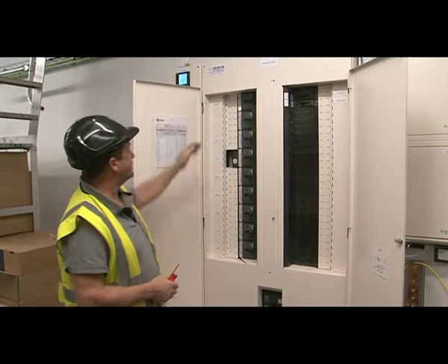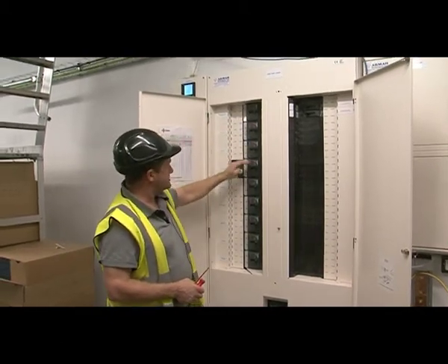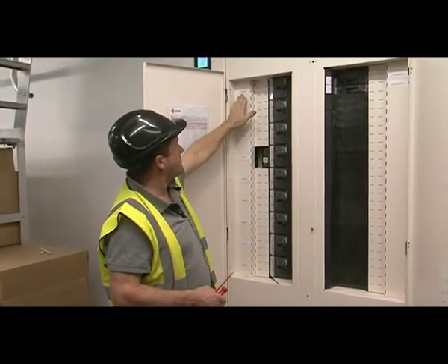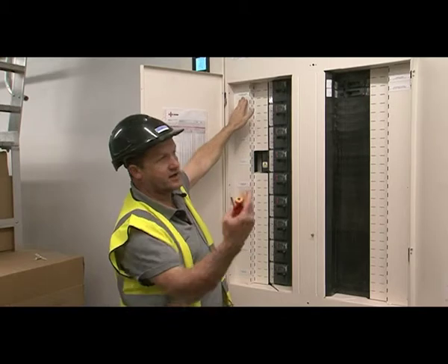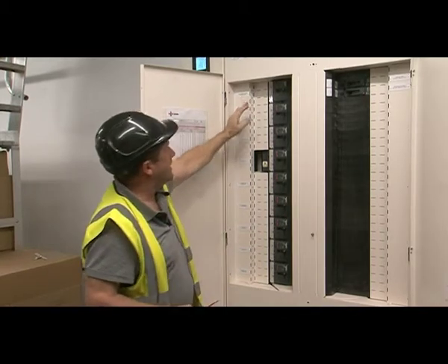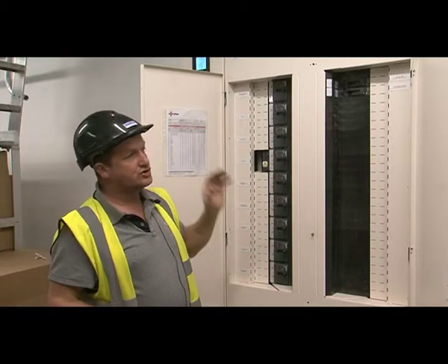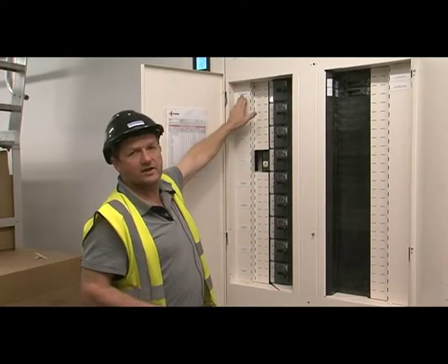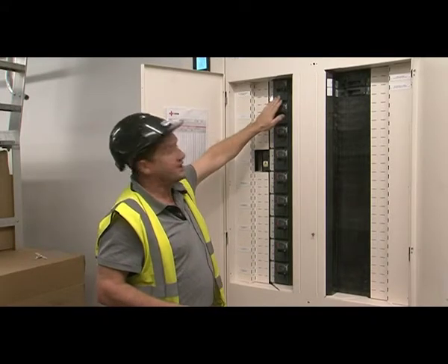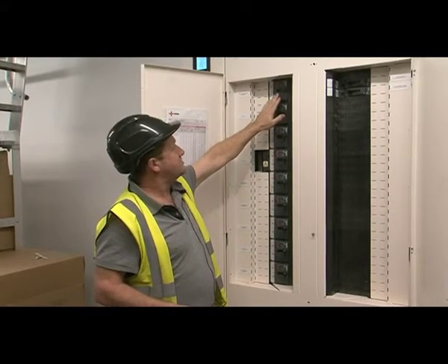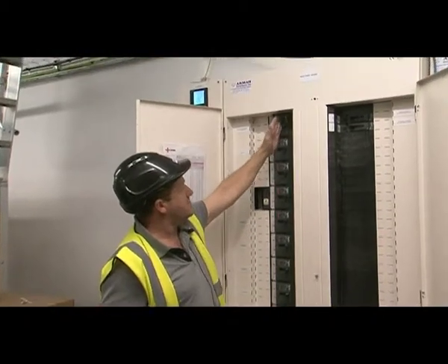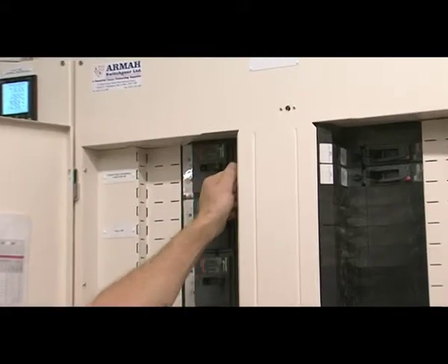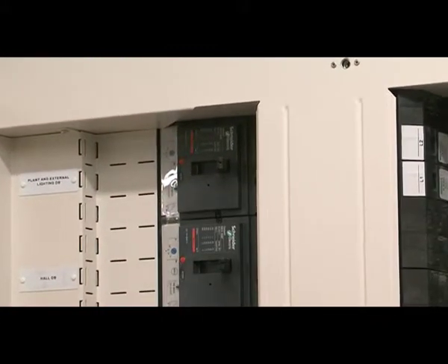Inside the distribution board, each of the moulded case breakers relate to what they are labelled as. So the very first one is the plant room and external lighting distribution board, again alongside in the plant room. It is very rare, but should you lose all power to that distribution board, plant room and external lighting DB, this breaker may have tripped. To reset the breaker, it will be in the mid position. You push it hard to the left and then extreme to the right, and that will reset the breaker.